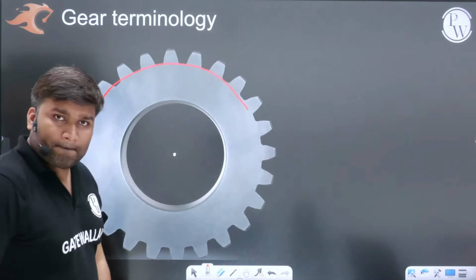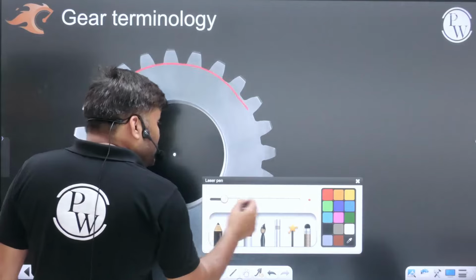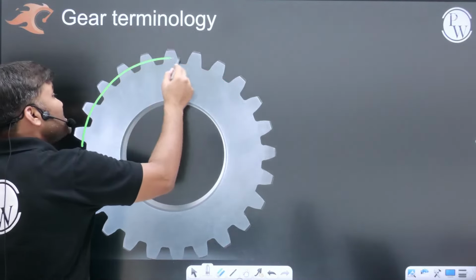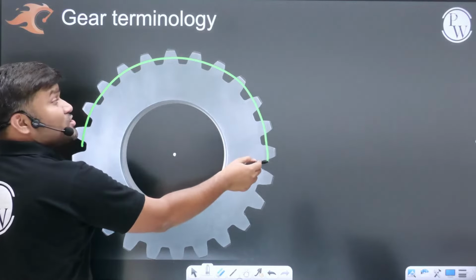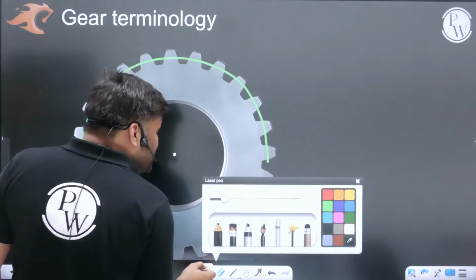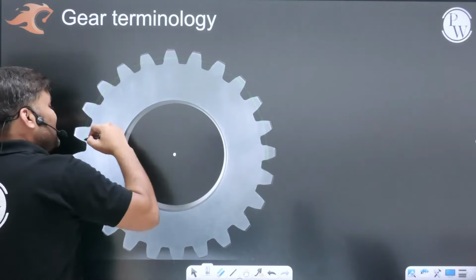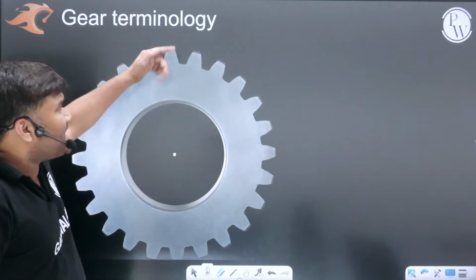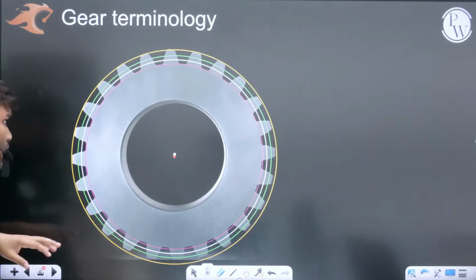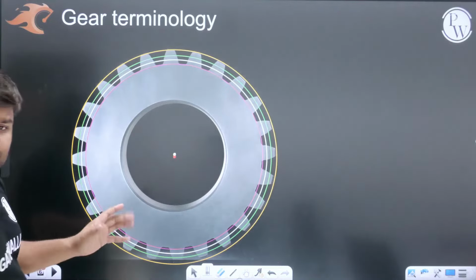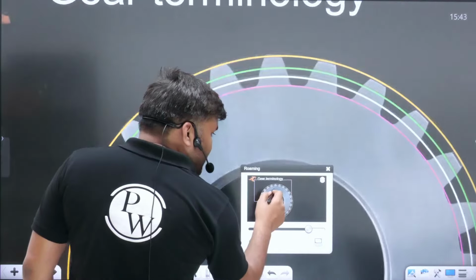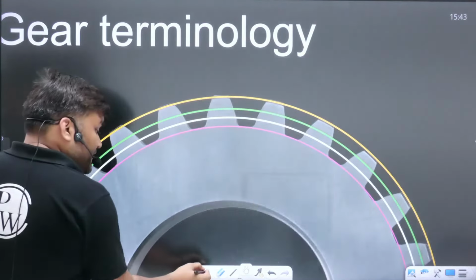Beta, if you draw a circle at which pure rolling motion can be imagined, this circle is known as the pitch circle, and then there will be the base circle for which you have drawn your involute curve. That base circle is a little bit lower than this pitch circle. Beta, if I draw all these circles all together, it looks something like this. Let me zoom this diagram and give you a very, very clear idea.